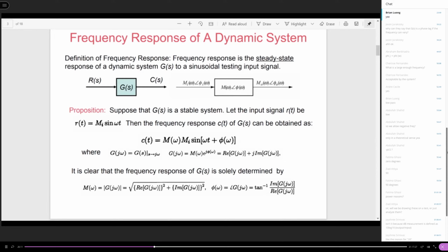But if you use a periodic triangular wave, you can only catch the response to certain frequency values, not all of the frequency values. You see what I mean? So that is why conducting the frequency response here is good enough. I do not need to use other kinds of periodic testing signals.